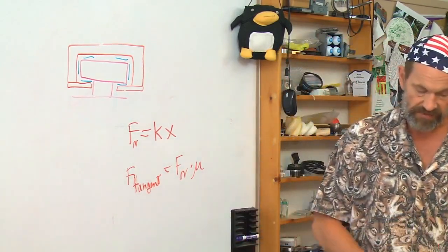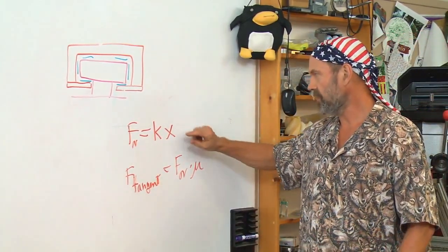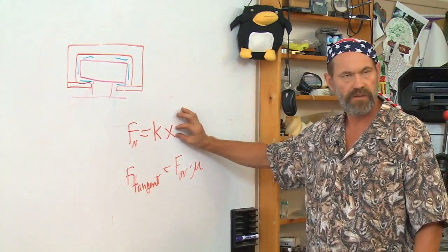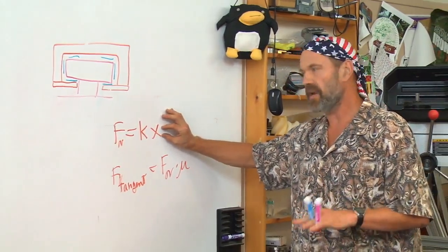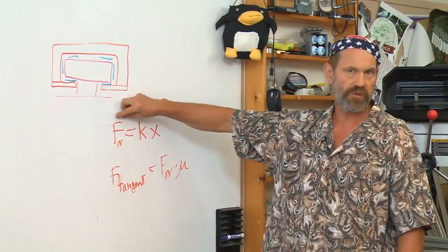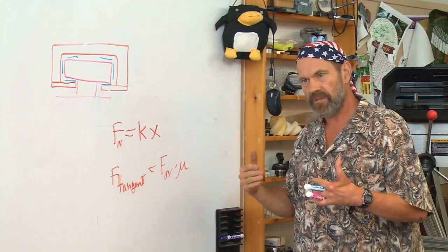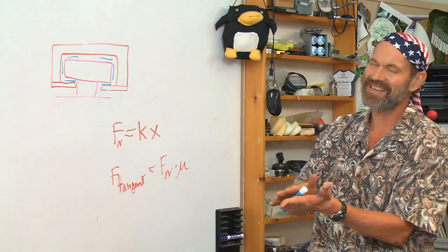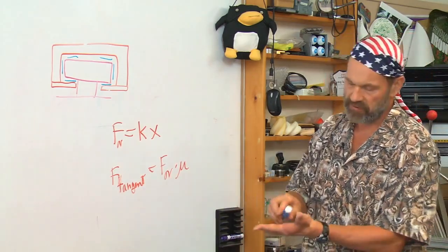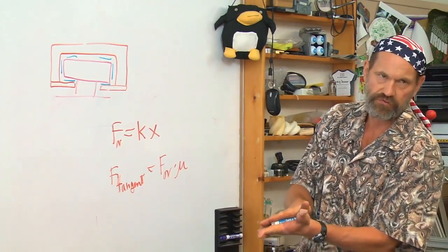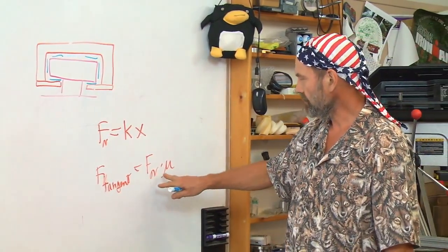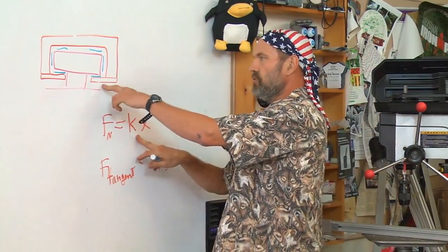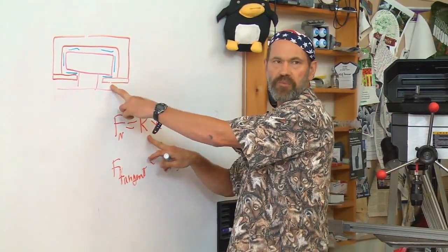So you've got to be very careful that if your bearing is very stiff and you have a small motion deflecting the bearing, it can cause huge normal forces. In a rolling element bearing, you may not feel it because the rolling element has such low friction. Whereas a sliding bearing, you'll know it very quickly. Oof. This K here you can control with the shape of the structure and how you preload it.